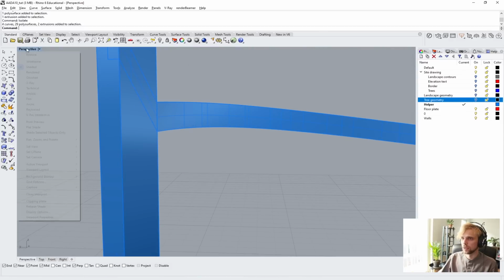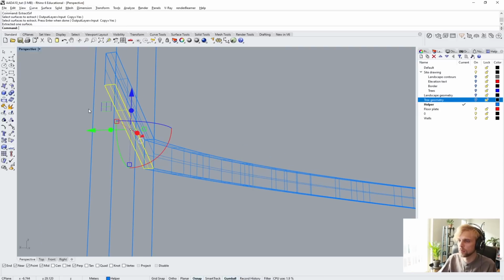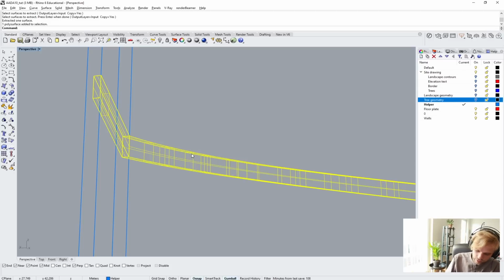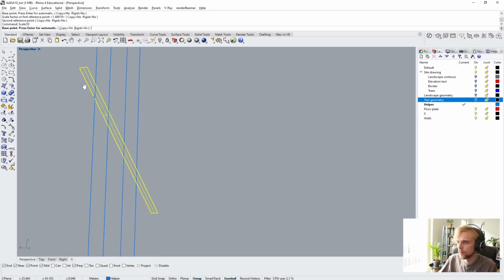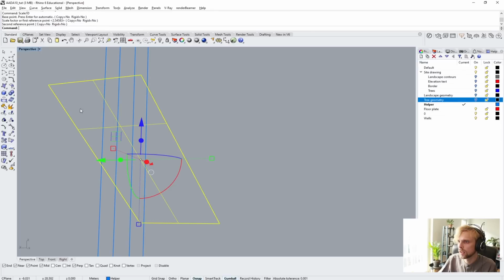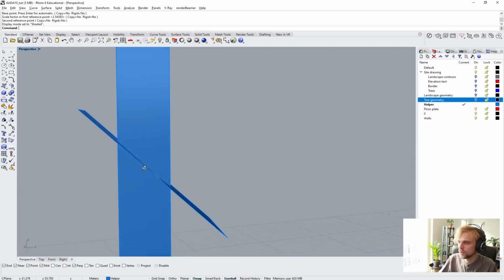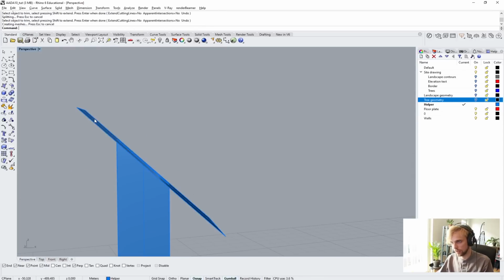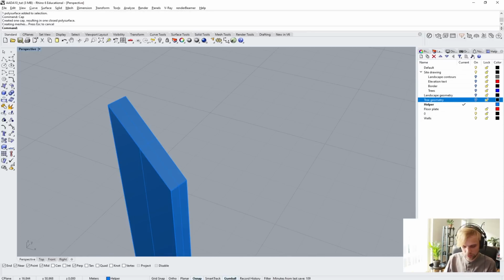And actually from the ribbon, if I remember correctly, I'll go to wireframe, I will extract surface because I only care about the bottom surface. That's how far the box should reach, just the bottom surface. So I just extract it and I hide the ribbon, and now I will use scale 1D to scale up the bottom surface in a way that I want, so that it definitely intersects with the box. And then I will use it to trim away the top of the box. Then I will delete it and select the box and cap it to create a top surface on it.